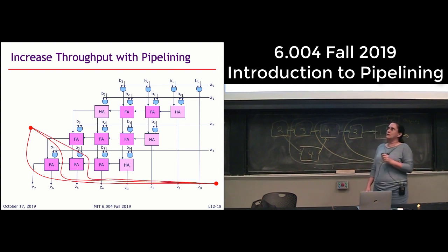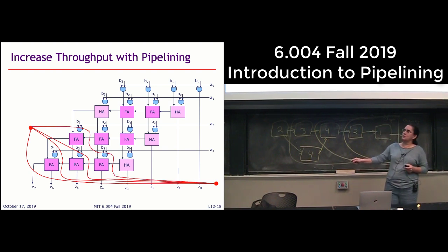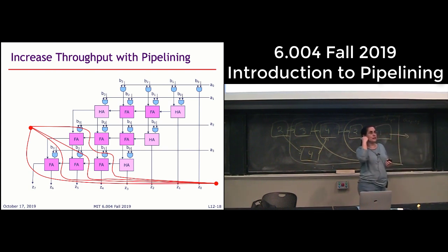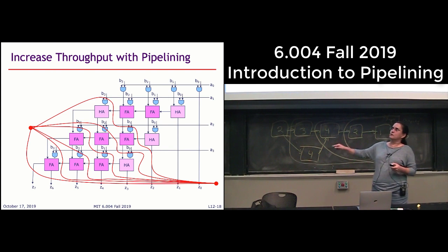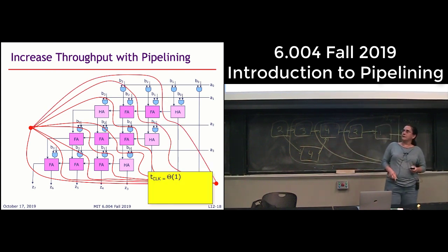All right, now I do another contour, which isolates this full adder. But on the next step, I notice that I can actually put these 2 full adders at the same time because they're independent of each other, okay? So they can be in the same pipeline stage. And so I continue basically drawing diagonal contours through this circuit as follows, okay?